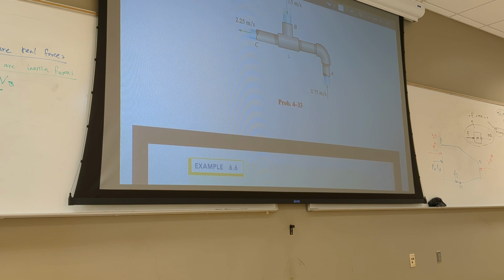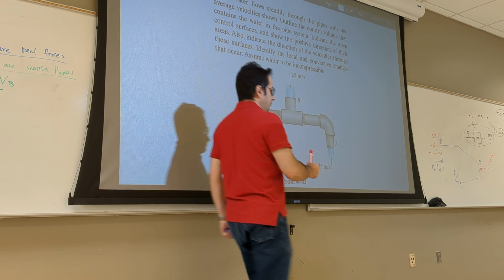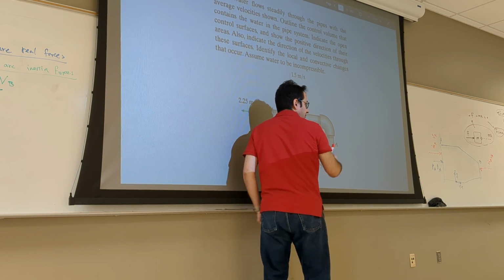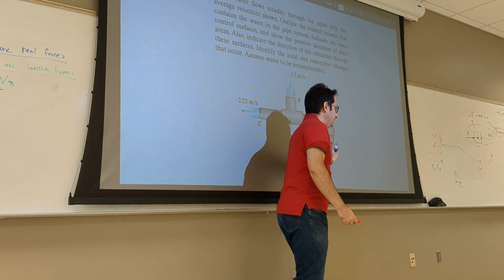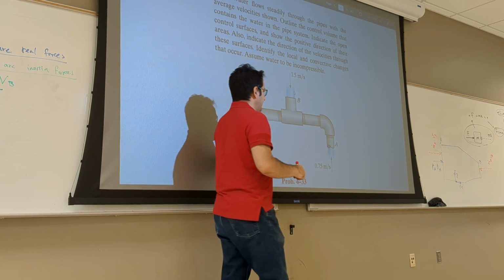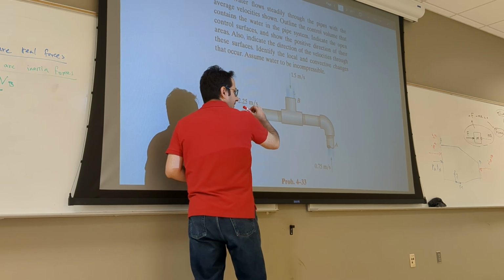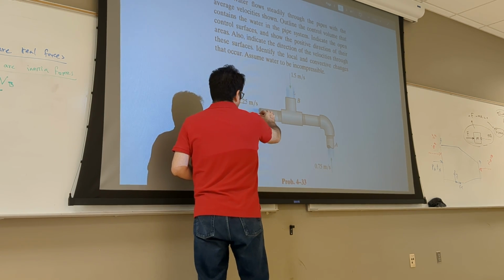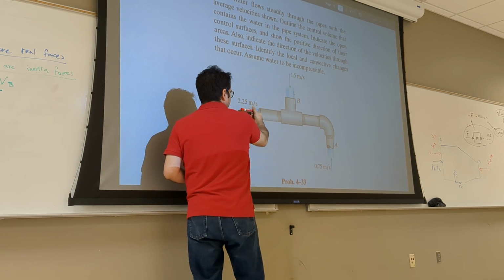So let's go down. You do not put pressure forces here, right? And then at A, it's inside the pipe. You see this cut? That means you're cutting a pipe. So inside that pipe, PA. If there is no reaction, that's it. That's a real load. Now, inertial loads. There is one here, positive direction. V dot N is positive, times this, so the actual thing is this way.